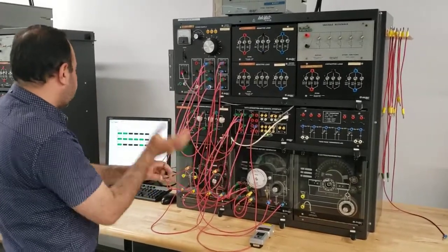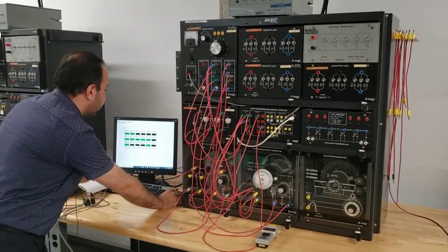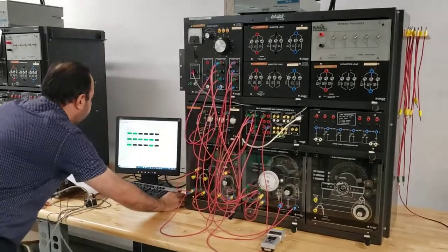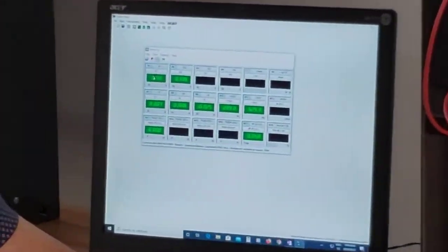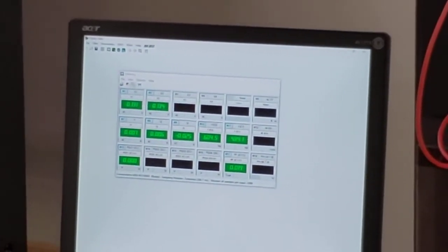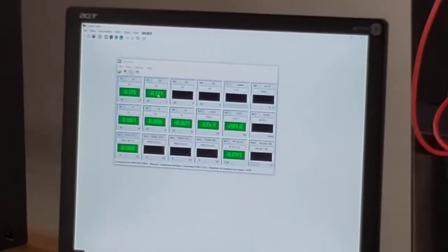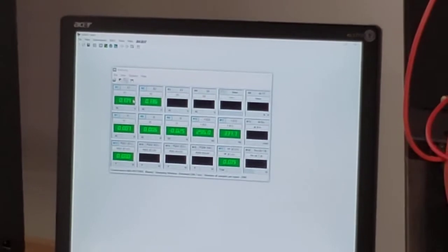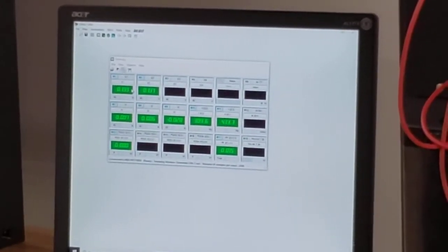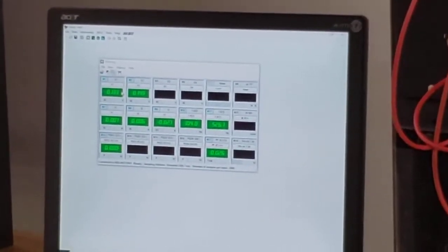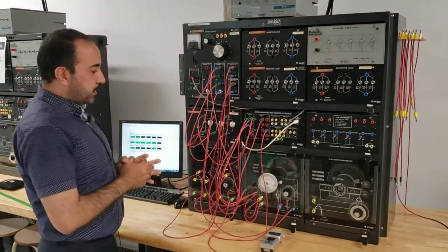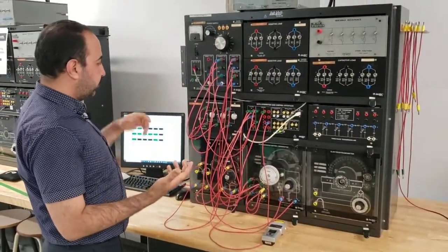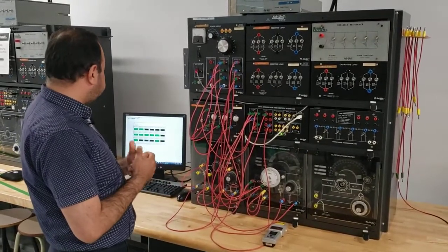And I will adjust my data acquisition system based on that. So E1, like what you are seeing here, is measuring the voltage for the synchronous generator, and E2, which is this guy, is measuring the voltage for the grid. Once they are equal, this is the first condition, I can connect if the other 2 conditions are valid. What I need else for the connection, I will try to connect my circuit and see.